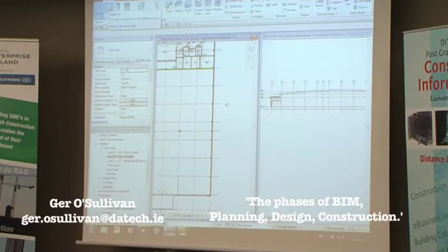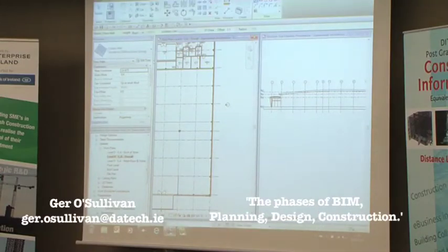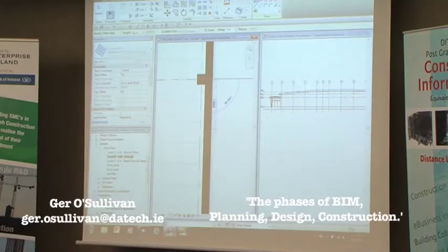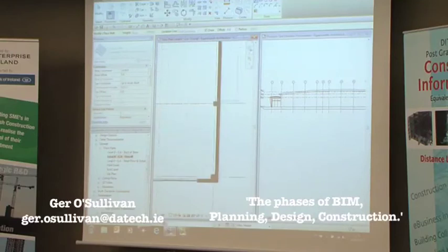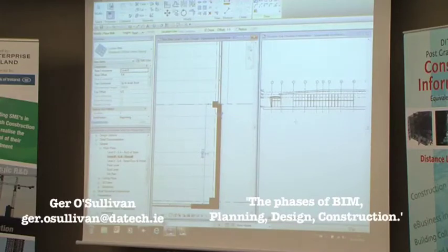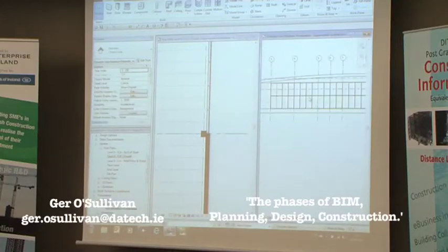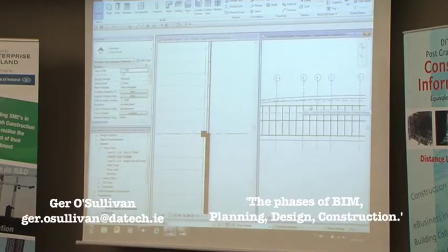So when I go to draw a wall in this case, I'm inputting properties, like the type of curtain wall it is, where I'm just picking an existing one, the level that I'm drawing it from, and the height of it, all being controlled by the actual model. And again, the pattern, what makes up this curtain wall, and how it's going to look. So let's just draw it and we'll see what happens. We select a point within an existing wall here, scroll down, and finish off the curtain wall like that. And what you should see happening is it being added instantly. The minute it gets added to the plan, it gets added to the actual elevation like that. Okay? So you're seeing the same information on both views.